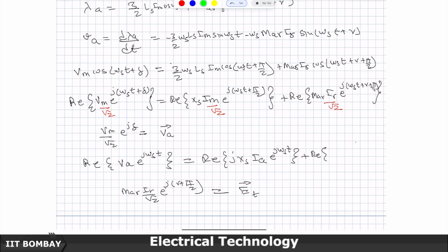Then you connect it with a step up transformer, so bring it maybe to 132 kV, 220 kV, 400 kV, whatever, connect it to the grid, then the grid takes it around here, there, and then steps it down, and then it is used. You don't generate it at 400 kV, that we have seen in the transformers story also.